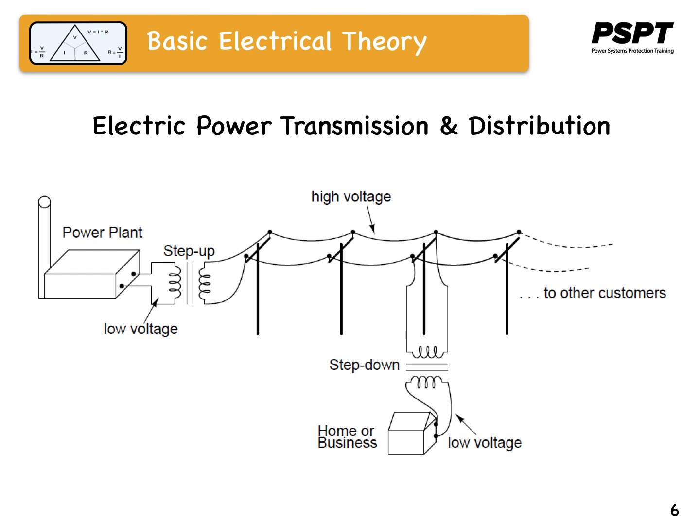As useful as transformers are, they only work with alternating current, not direct current, because the phenomenon of mutual inductance relies on changing magnetic fields, and direct current, DC, can only produce steady magnetic fields. Transformers simply will not work with direct current.